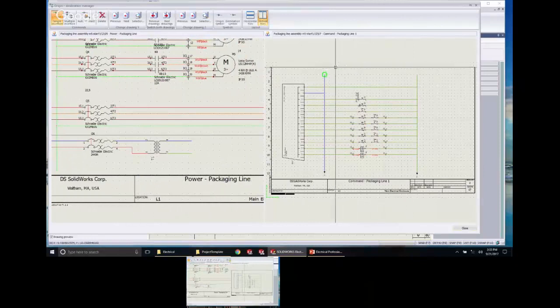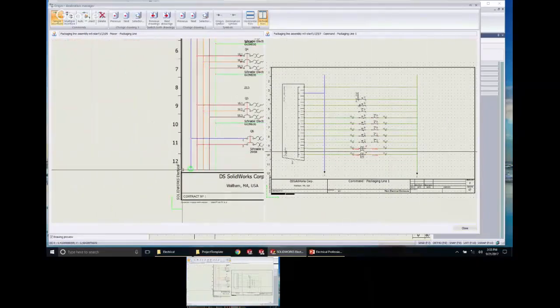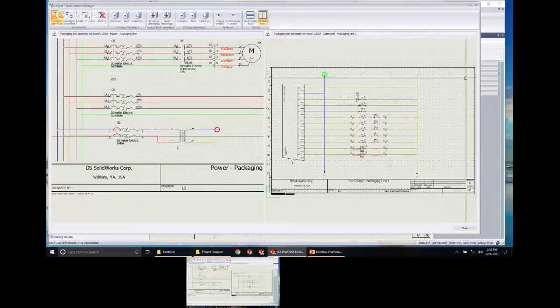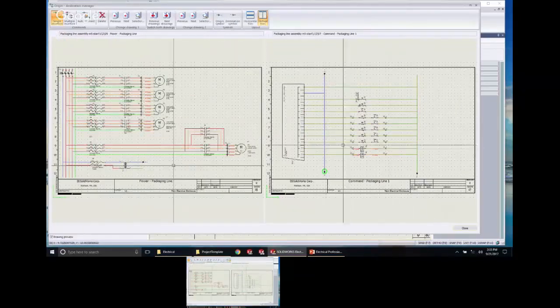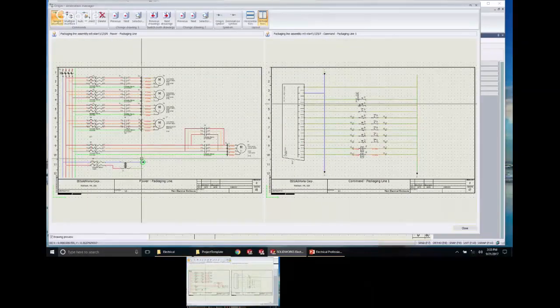So I can select any of them, right? But when I select one, for example that neutral wire, notice I can no longer select anything that's not a neutral wire. So origin destination arrows is another way. It's not going to let you make a mistake. You can't pick another wire style. I select that one. It creates the arrow.